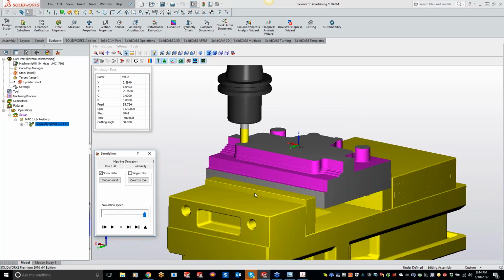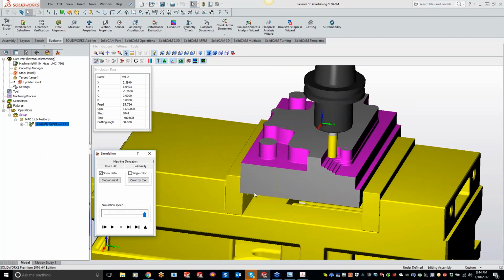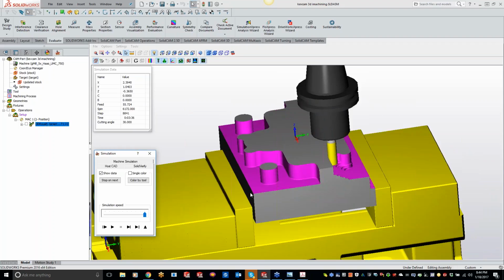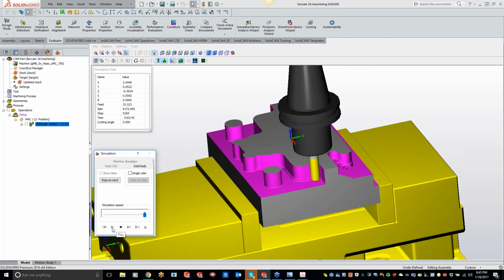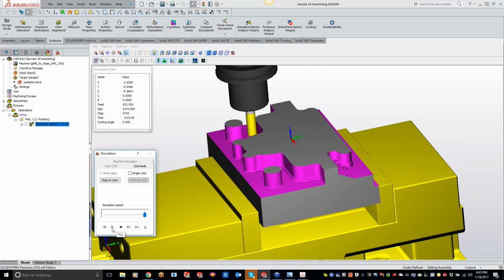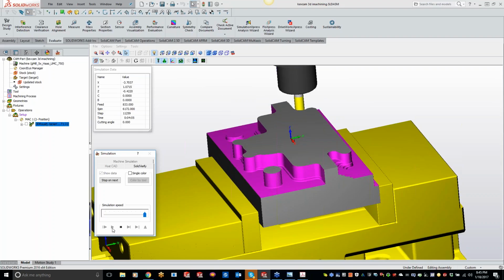A lot of times in regular toolpaths, with normal or conventional cutting, where it breaks through that wall, it just continues at the same feed rate, and then all of a sudden the end mill's tooth might catch on that particular side, and you could get a tool breakage there.